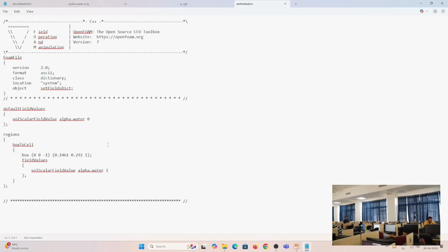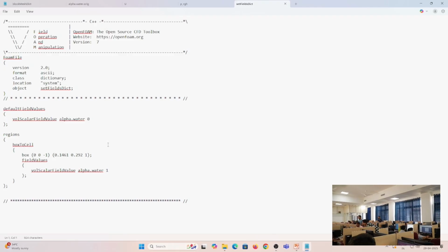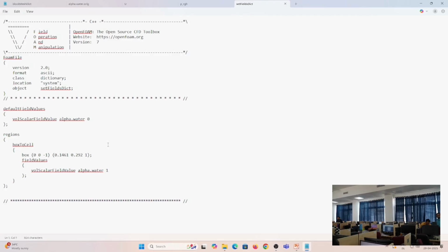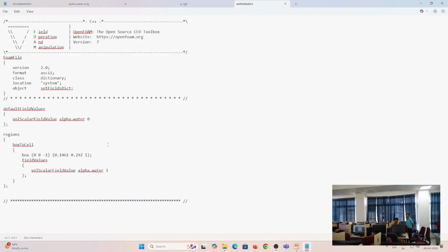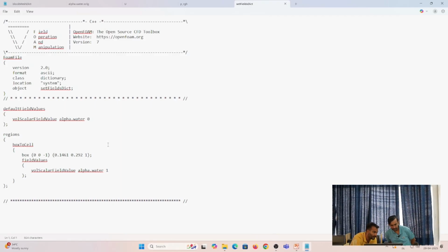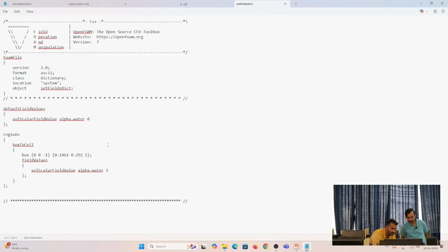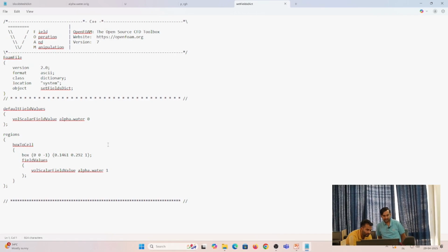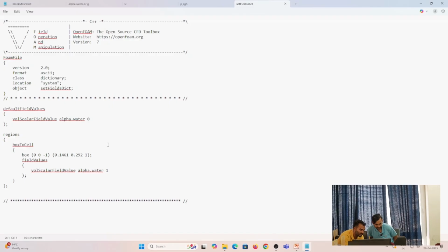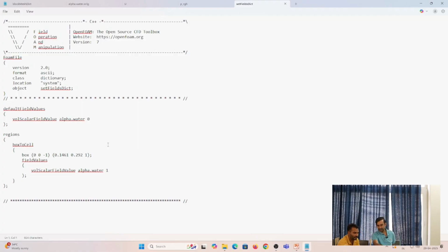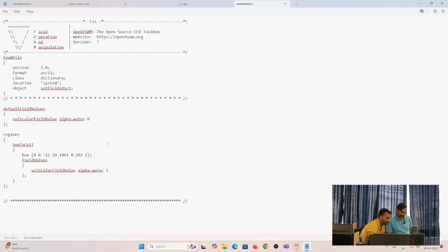After this, please go to ParaView. In the same terminal, please type paraFoam. Skip 0 time, confirm.